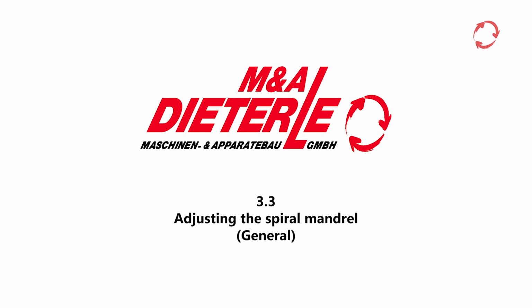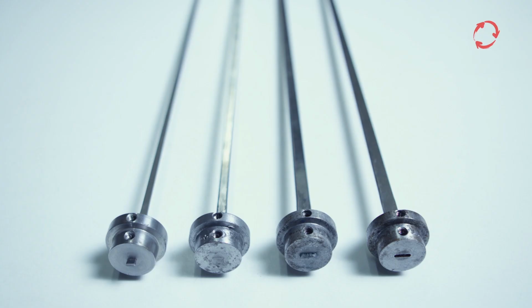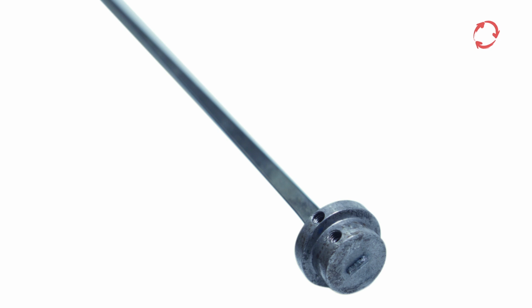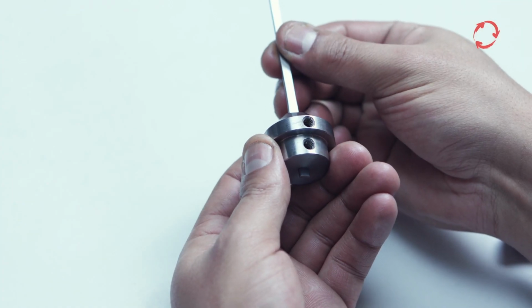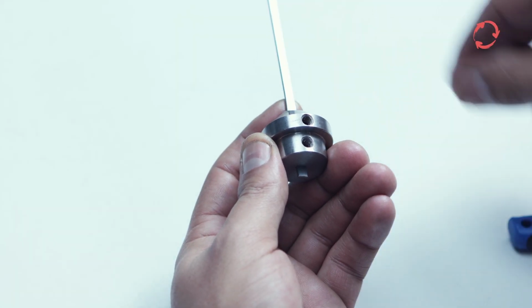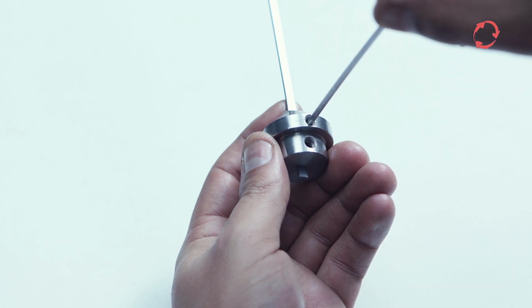The spiral mandrel is typically only adjusted when a new mandrel is used for the first time, or when a different spiral size is required. The spiral mandrel essentially consists of two parts, the mandrel itself and the head. The mandrel can be moved up and down in the head, and is locked into position with two threaded pins, using an Allen screw.